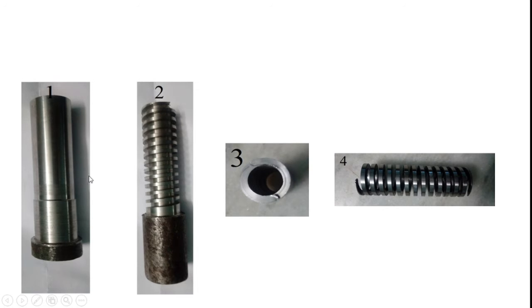First step, I turn the workpiece. Second step, I form the thread on the workpiece material. Third step, center drill, it makes the center hole and removes the excess material from the workpiece. Fourth step is cut the spring. The fourth step is to cut the required spring from the workpiece. These are all the steps available with spring manufacturing on the lathe.